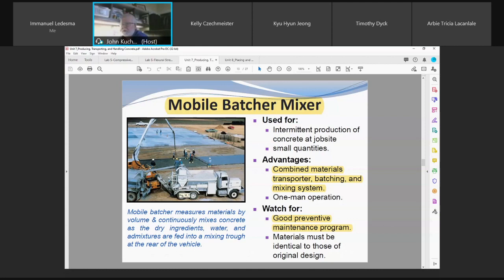Here he just keeps mixing. Once the box is filled, the forms, he's done. No waste, no under, no excess. Because he's continuously batching until he fills the forms. So it's good in a way, but the fact is the consistency of it sometimes is in question. If these things aren't calibrated properly, your mix can create havocs with you.